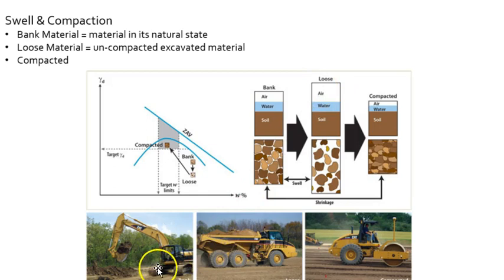So you would not just simply calculate the volume of the dig. You have to calculate how much that material is going to loosen up once it's excavated. And all different types of soil have a different percentage that they loosen up and swell. That's called the swell.